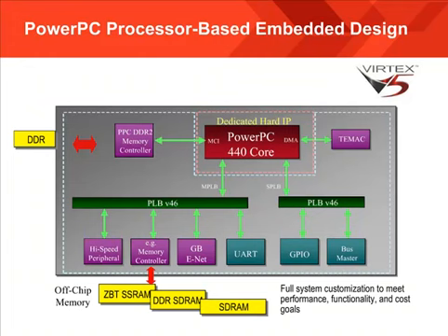This is a typical embedded system targeting the PowerPC 440. The PowerPC supports one bus standard, that is the PLB V46. The PLB is designed for 128-bit data and 32 bits for address lines. The PLB bus standard is designed for high speed and high bandwidth peripherals, and it supports dynamic bus sizing and a programmable burst size. The PLB bus standard peripherals are transportable to MicroBlaze embedded systems supported with other Xilinx FPGAs. This allows designers again to migrate peripherals from one embedded system to another.